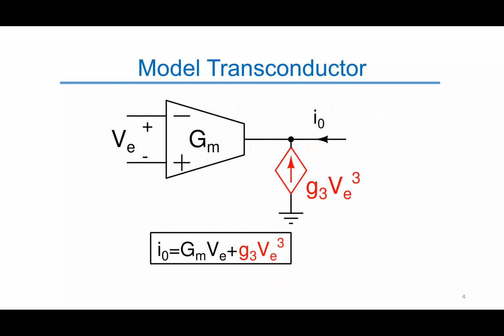Before we launch into analyzing these, let us talk about the distortion model that we will use in this study. We will assume that the dominant source of distortion in the transconductors is the modulation of the transconductance itself, and will be modeled as shown in the figure, and we will neglect the distortion emanating from the modulation of the output conductances. Also, we will assume a fully differential implementation of the architectures and will neglect the even order non-idealities. Further, we will also assume a weakly nonlinear system and will limit our discussion to third order nonlinearities only.